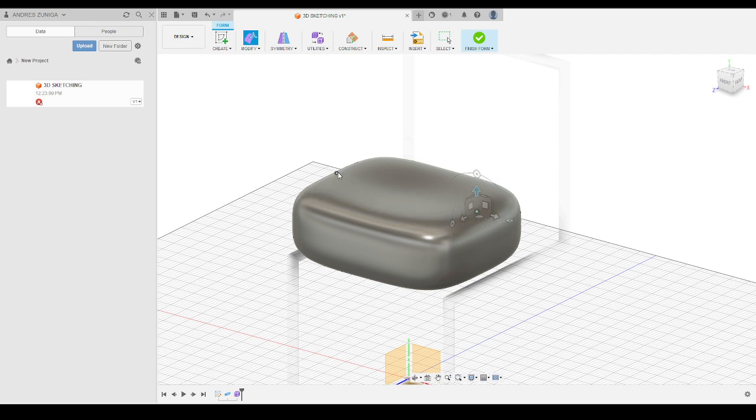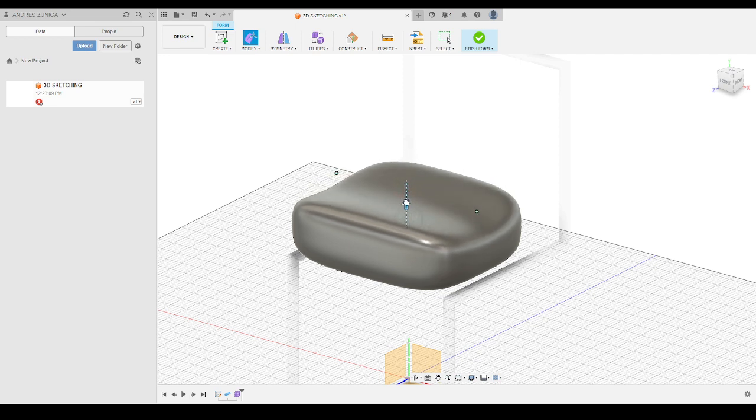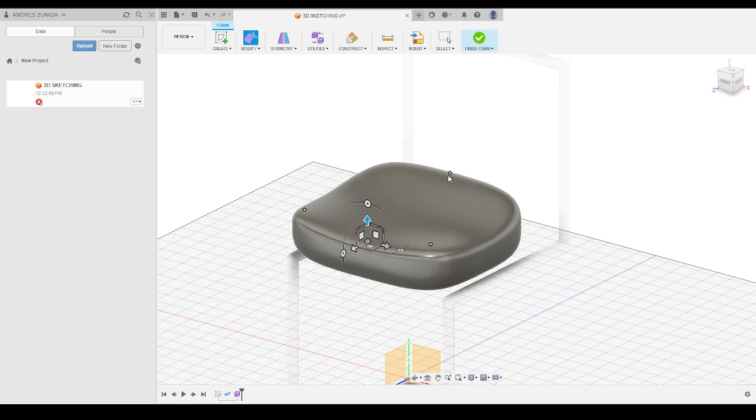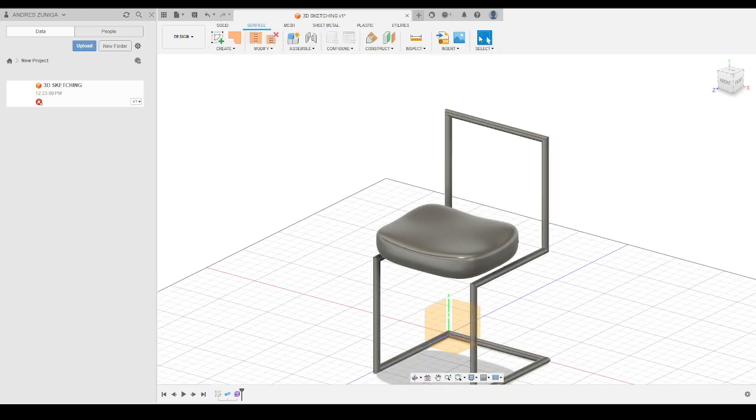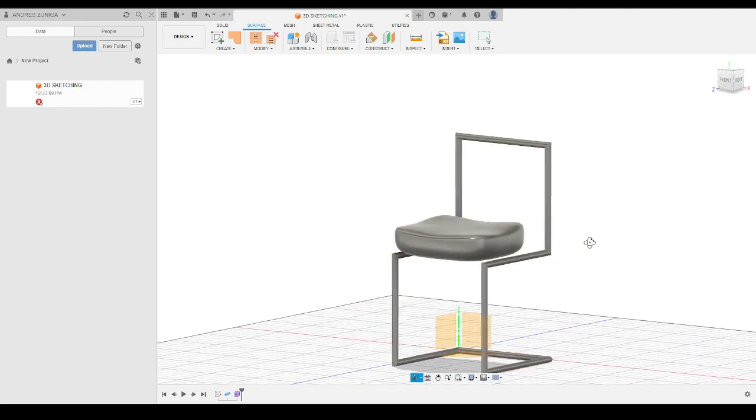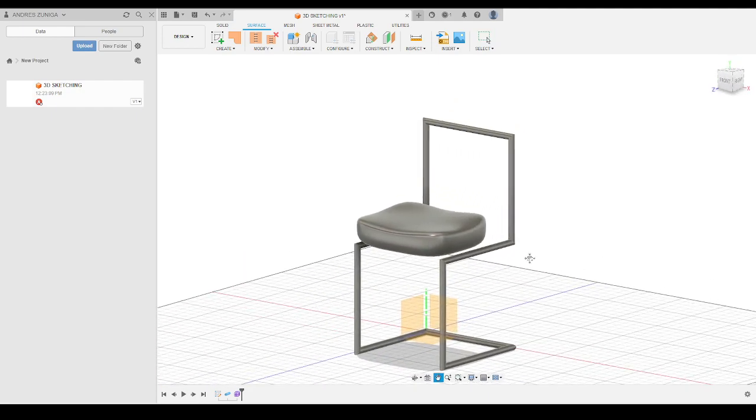Then I can select different points also with the shift button, and you can see that the cushion can go down, like a real cushion. And then I'm going to select this one right in the middle to see how this works. And you guys can start playing with all the different components and all the different things that you can do with this cushion, okay? Then I can make this one go a little bit down so it looks very clear. And then I can say finish form, and then I have the cushion that is going to be laying on the chair.